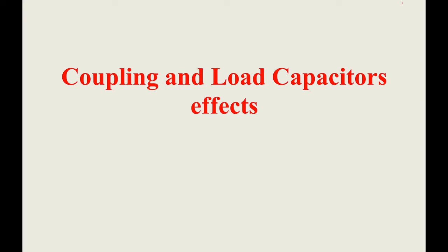Next topic is coupling and load capacitor effects in the common emitter amplifier circuit. In the last lecture we discussed the input coupling capacitor alone. Here we are going to see coupling and load capacitor. So that means we are going to derive two cutoff frequencies: for the coupling capacitor we will derive FL, and for the load capacitor we will derive FH.